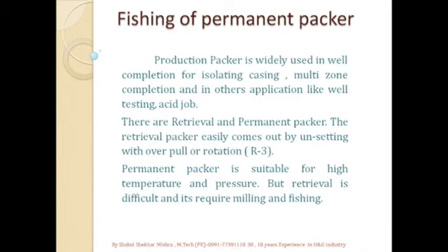But the permanent packer is widely used where we have high temperature and pressure, but its retrieval makes it difficult because it requires milling and fishing, which in turn consumes longer rig time.